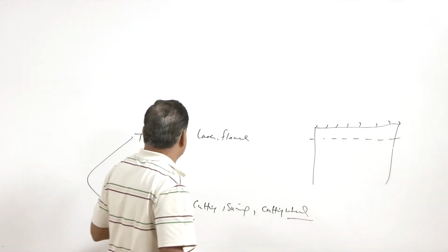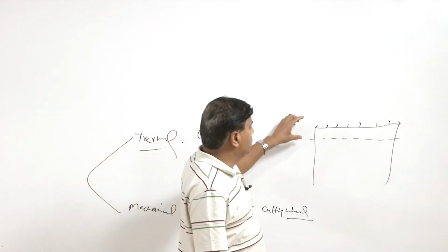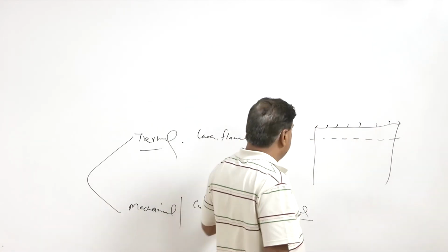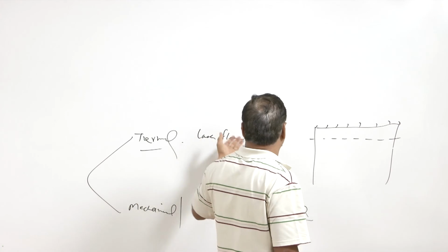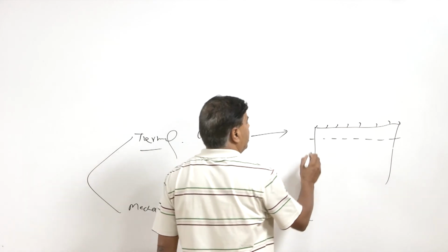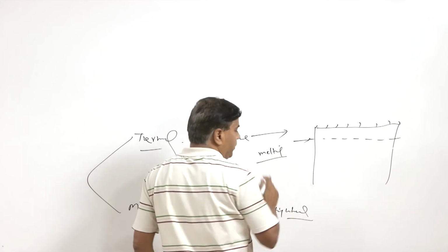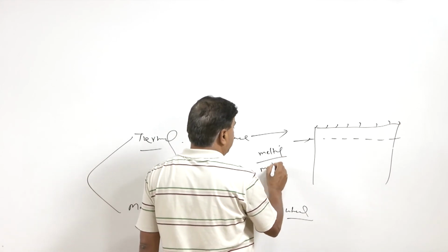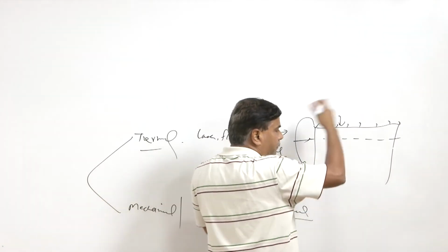With both these methods, whether we apply the thermal method or the mechanical method, there is a possibility of damage to this region due to the mechanical loading, or due to the use of cutting fluids during machining, or due to the heat generated during the cutting, or whenever a laser or a flame is applied. In thermal cutting we basically do controlled melting so that the sample can be removed. Whenever melting is applied there will be molten metal, and this molten metal can fall onto the surface, so such falling has to be avoided.